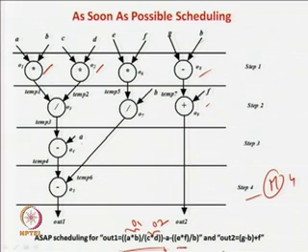Now, E star F we can do immediately. So, we have put E star F, O6, in time step 1 because there is no immediate predecessor. But this divide by B we cannot do right now because it depends on the output of E star F. Now, for this other expression we know that G plus B can be done in time step 1 because the variables are directly input, so O8 can be scheduled in time step 1. So, operations like O1, O2, O6 and O8 we can schedule in time step 1 because they do not have any predecessor, their values are directly from the input.